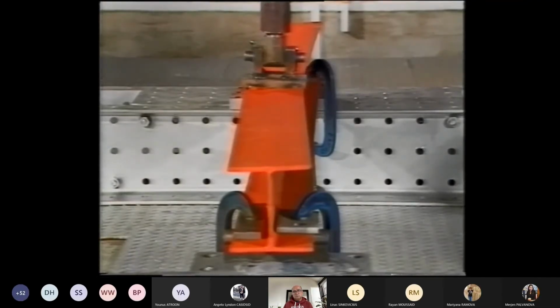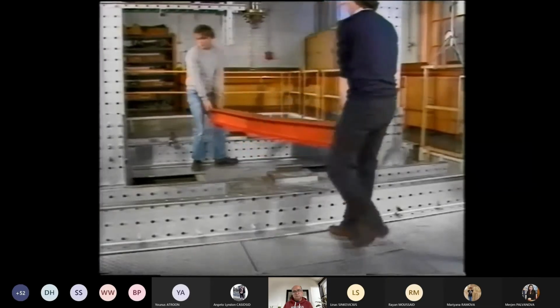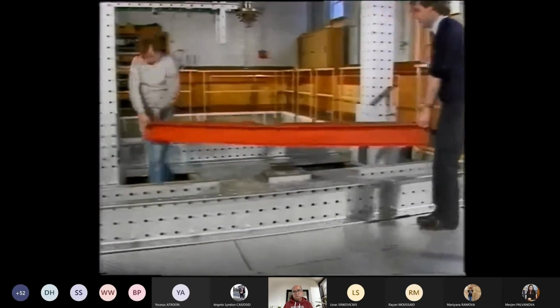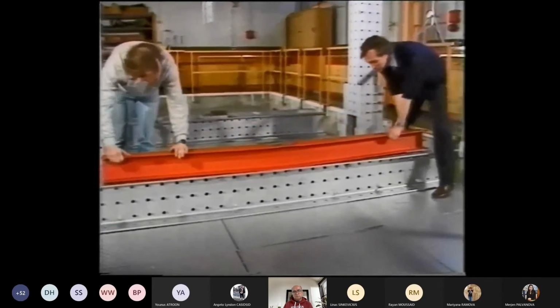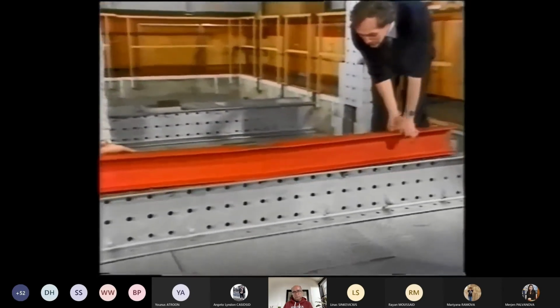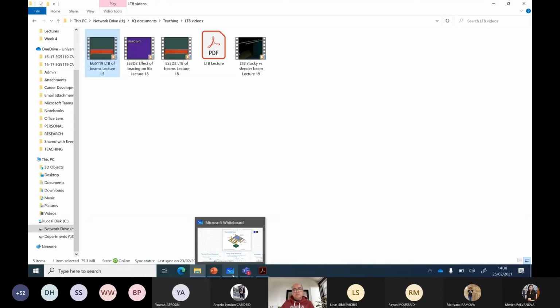It can be seen that lateral deformation and twisting occur, together with plasticity. Removal of the load is accompanied by only partial recovery of deflection, and significant permanent bending remains in both principal planes. We're trying to target this intermediate range where the plastic capacity and elastic critical moment, both of them, interact.